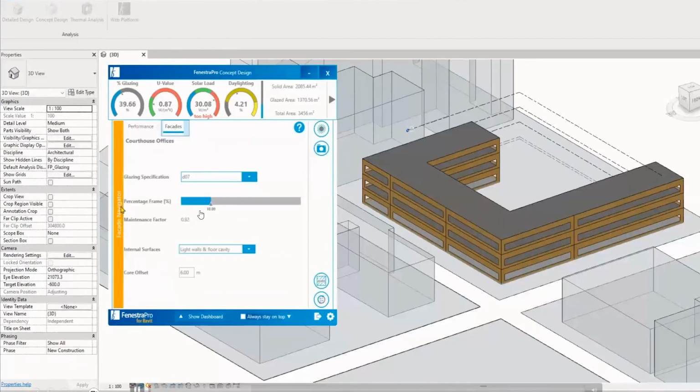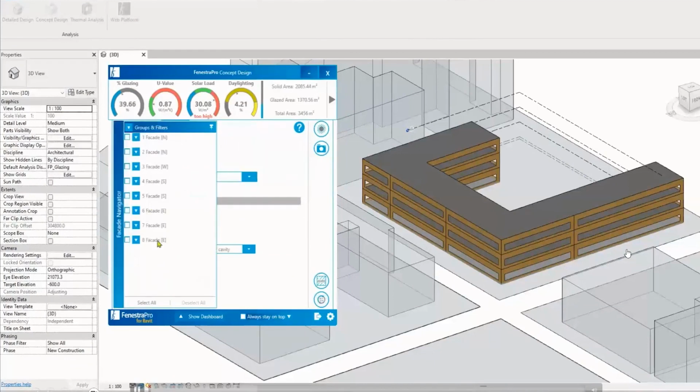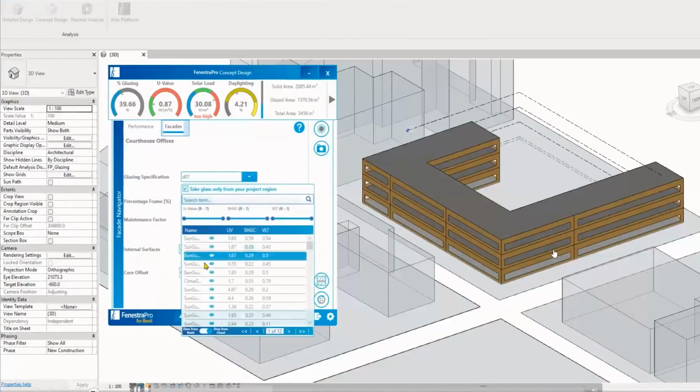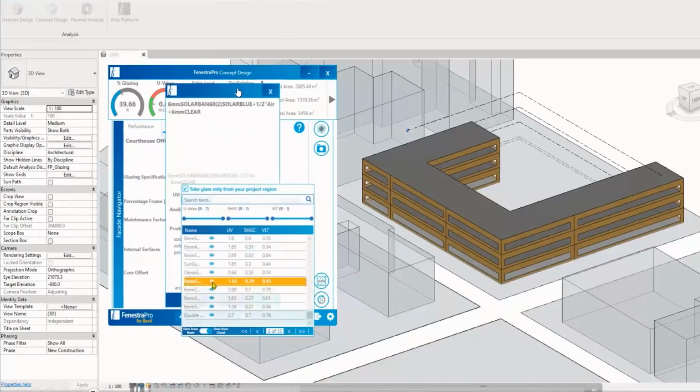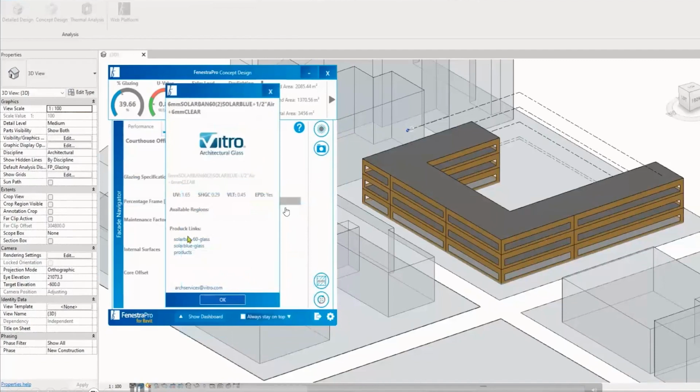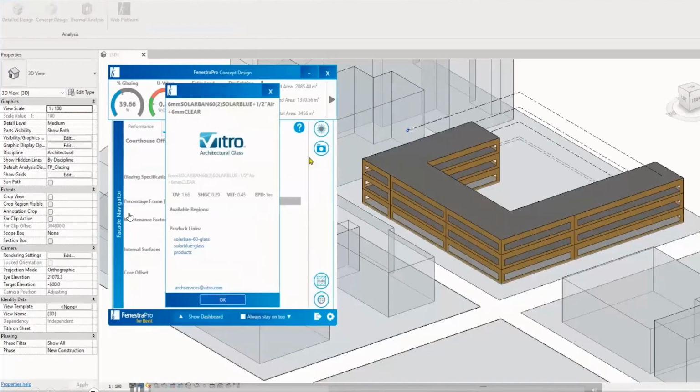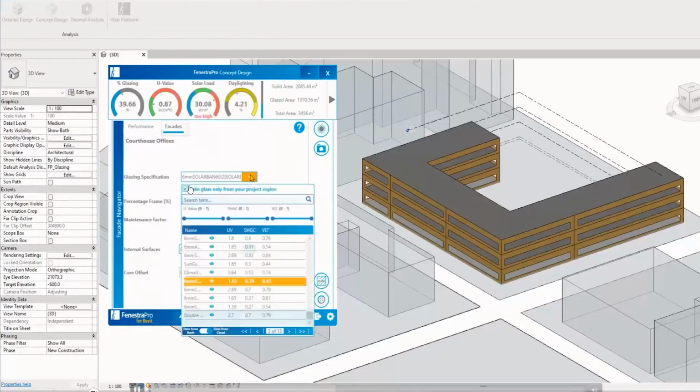You see in that instance where we've established 40% glass, that 40% is then written to the model in the form of these notional openings. And then you can see where we're getting good thermal performance values in terms of the U value. We're looking at where we're getting a slight overheat and where we are sitting with the daylight. We can then select different components based on those performance criteria. For example, glazing. In this instance, we can see a Vitro glass that might address these overheats.